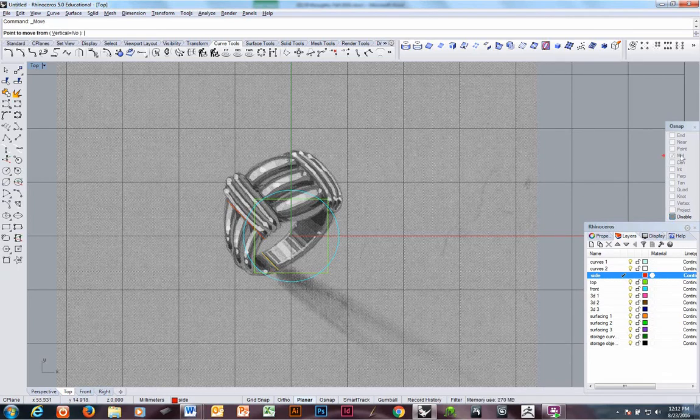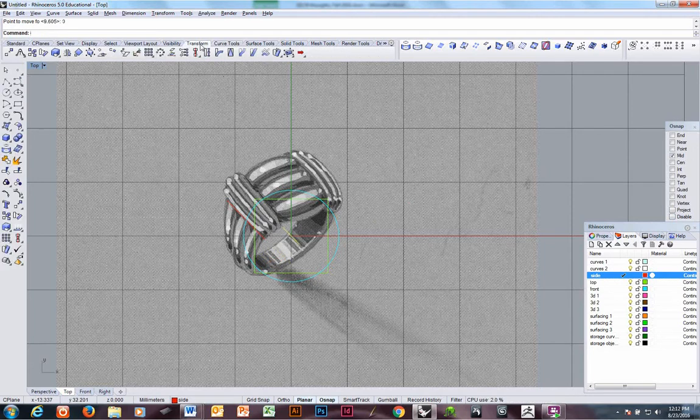Going to go ahead and grab this from its midpoint, put it in the middle, rotate it, mid-end, shift key, and pull it off to the side. I don't really care how far at this point. Move this from midpoint to 0 and rotate it. Once again, midpoint, endpoint, shift key. I'm going to grab both of these and move them out to a little bit beyond the outside of my box here.